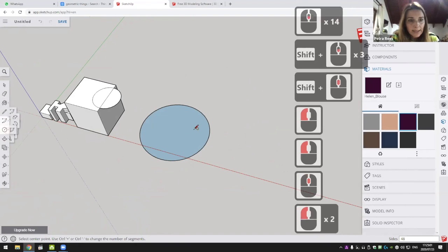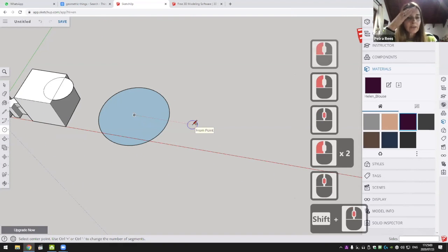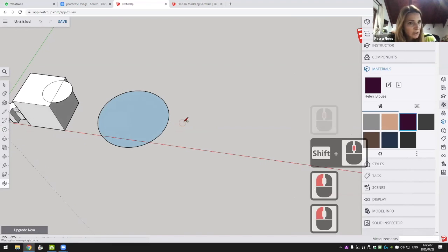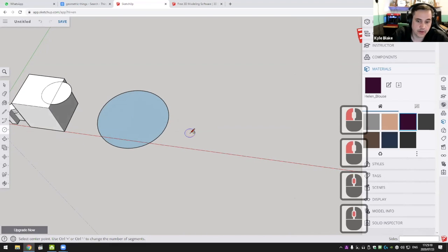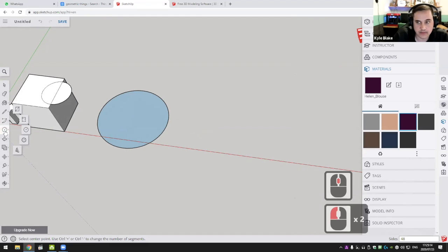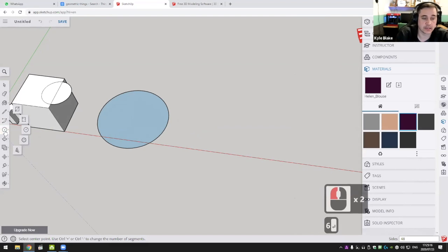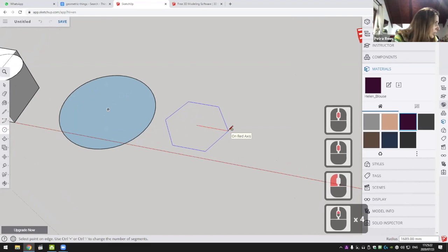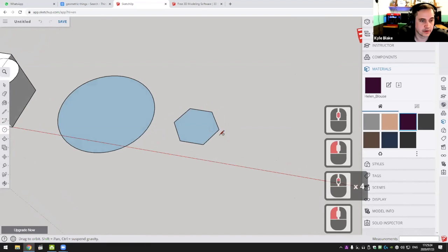I can't see the, sorry, where did you say is the circle update? Sorry, with the size? The sides. So the bottom right-hand corner, when you first click on the circle, it shows sides, bottom right, and you can actually type in. So you can say you want 6 sides. Oh, there we go. Yeah. Got it. Thank you. And then you can draw a 6-sided circle.